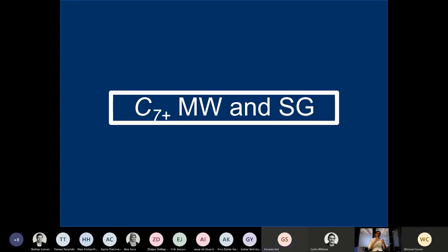What we talked about yesterday, we've been talking about it today. We're going to talk about it also tomorrow in C7 Plus characterization, is capturing this relative paraffinicity and aromaticity of a particular field. And I think yesterday you did the calculation of the Watson characterization factor for these two PVT reports that we have. You can just plot the measured molecular weight and the densities of the entire stock tank oil, but you can also back calculate properties